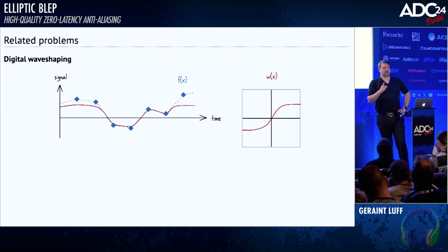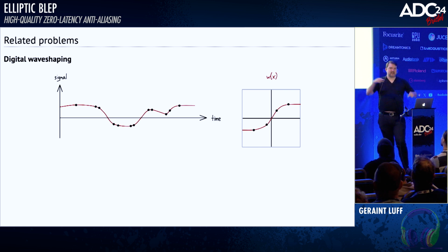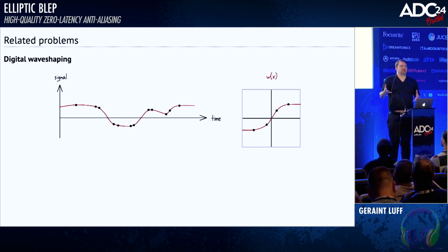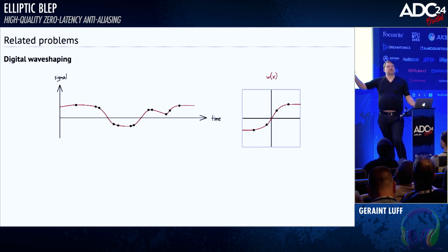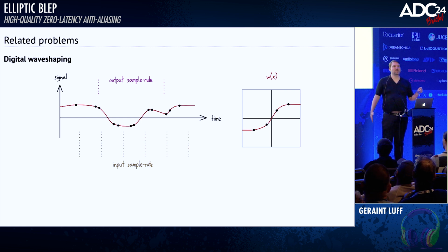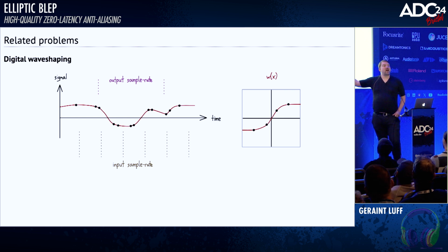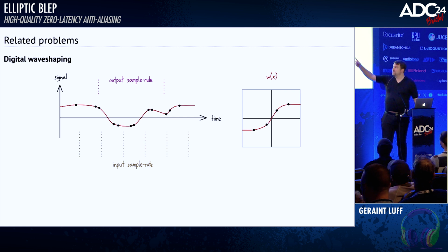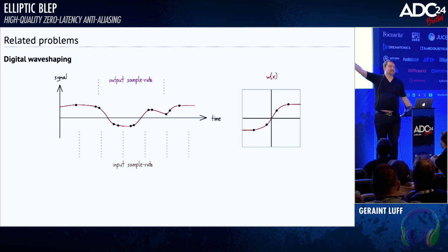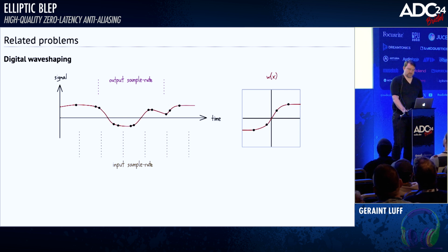But if our waveshaper is made out of polynomial segments, then our distorted wave-shaped curve is also made out of polynomial segments. You've taken a linear section of signal, stuck it through a polynomial function. The output is just polynomial segments. So if we can solve this polynomial problem, then this gives us quite a nice way to anti-alias digital waveshaping. Plus, because we're now in continuous time and we've low-passed, your output sample rate doesn't have to match your input one at all. So you could, for example, upsample your input, as you might do when oversampling, do this polynomial segment thing, and then instead of sampling again and then downsampling, go directly to your output sample rate. Why not? Once you've got this polynomial segment stuff sorted, you can read out this continuous time signal at whatever time positions you want.